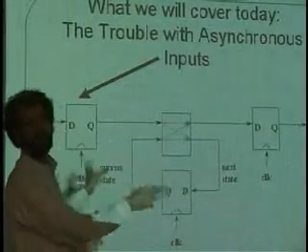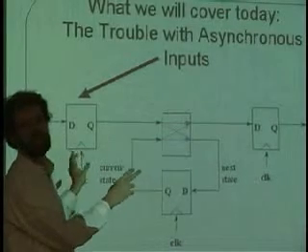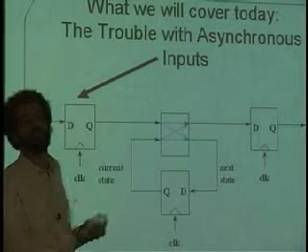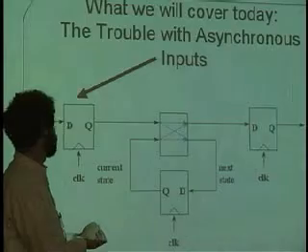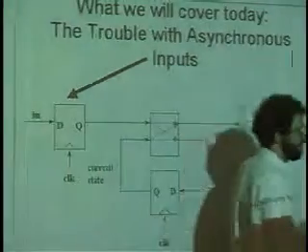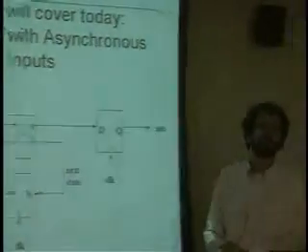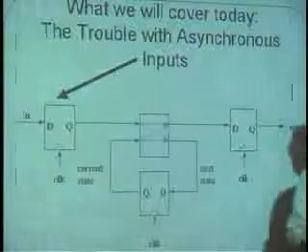I'm clocking all three of these guys at exactly the same time. They're all in sync with each other, plus or minus the clock skew, but we saw how to deal with that before. So this sounds great, except for one thing. What is wrong with this picture? Have I really solved the problem of this input changing asynchronously with respect to the clock? Have I really solved it?